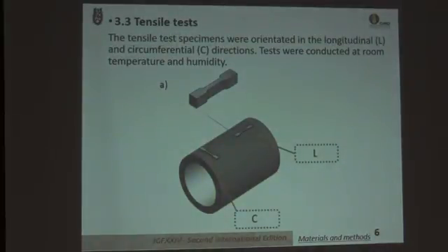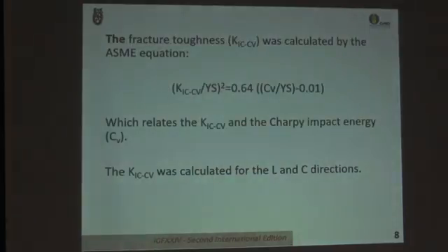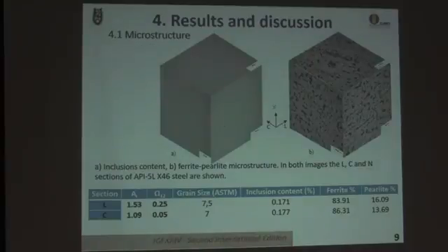Taking that reference, we made the tensile specimens oriented in the same directions, and the Charpy impact tests were made with the same characteristics. The fracture toughness was calculated by the ASTM equation, and then was compared with the microstructural characteristics.